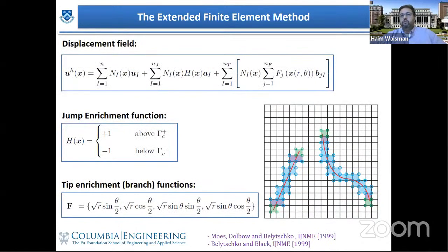So XFEM originally was developed by Ted Belytschko, the late Ted Belytschko, in 1999. And if you see here, there are two cracks which are shown here. Those cracks are enriched with two sets of enrichments. First, you see the first term here, this is the displacement field. The first term here is just the standard FEM shape functions. But in addition, there are two additional terms. This one, H here, accounts for the Heaviside enrichments, which are behind the crack tip.